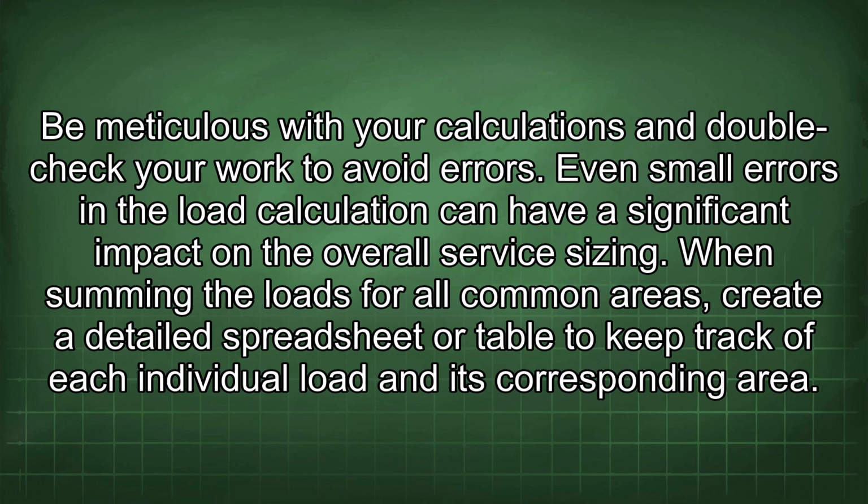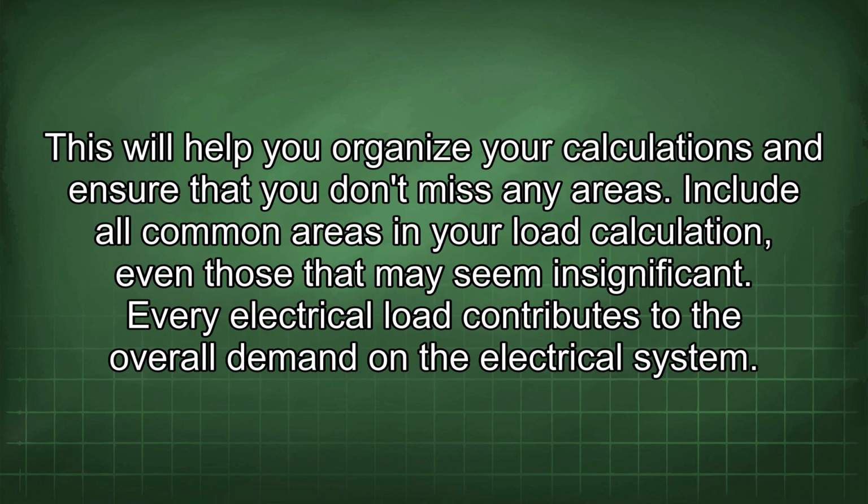When summing the loads for all common areas, create a detailed spreadsheet or table to keep track of each individual load and its corresponding area. This will help you organize your calculations and ensure that you don't miss any areas. Include all common areas in your load calculation, even those that may seem insignificant. Every electrical load contributes to the overall demand on the electrical system.